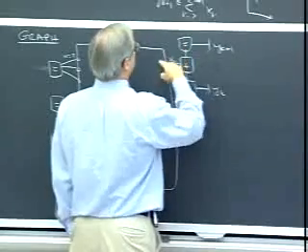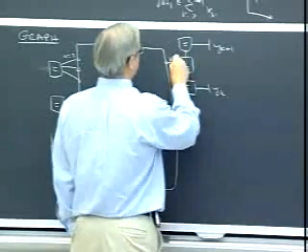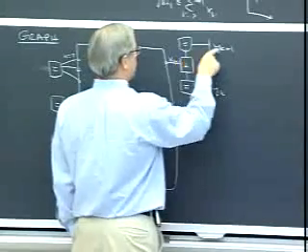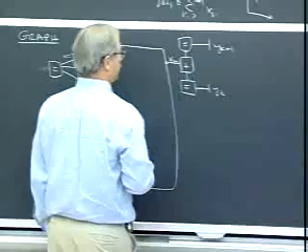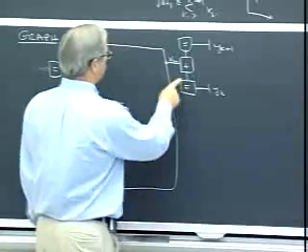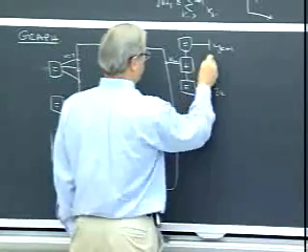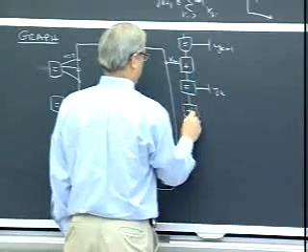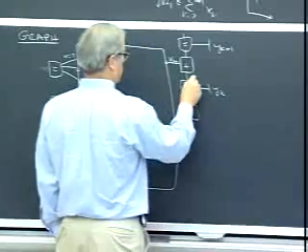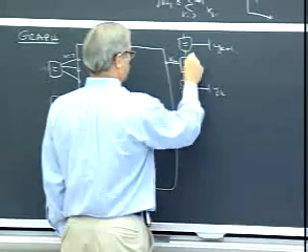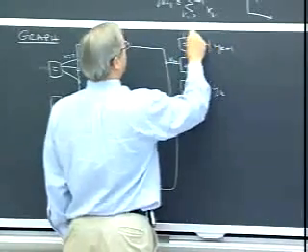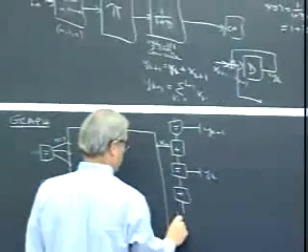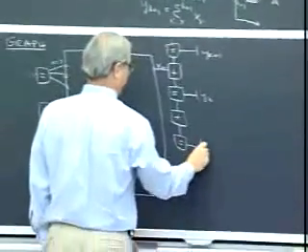I think it works either way, x_{k+1} plus y_k equals y_{k+1}. So this enforces the constraint. This is really the branch. This is just to propagate the y_k and present them as outputs. So this little two-state code, here's the state. The state is also the output. The state is what's in here. And this is what its trellis looks like.